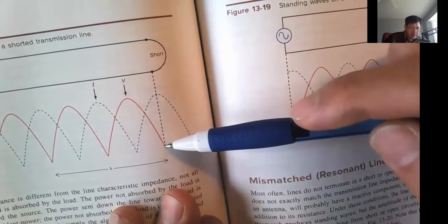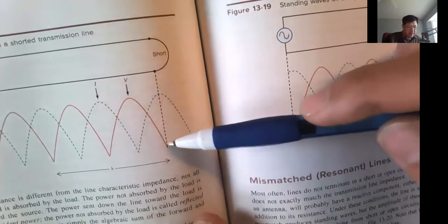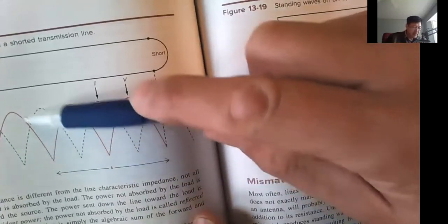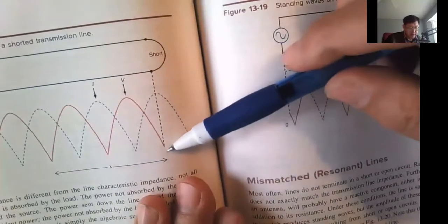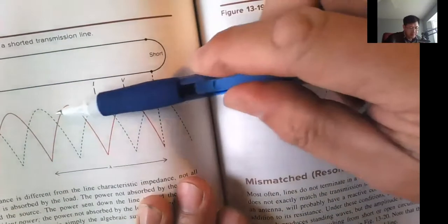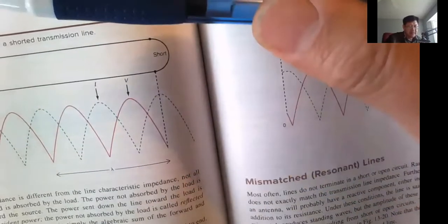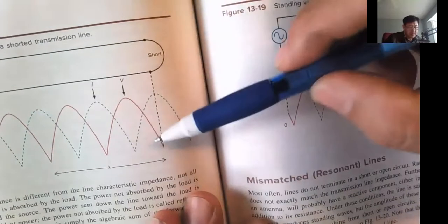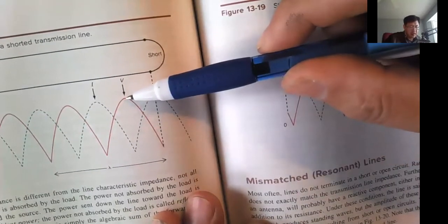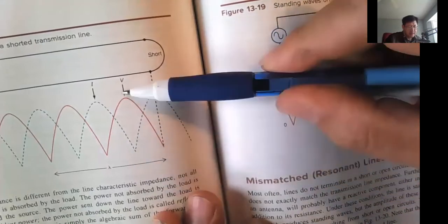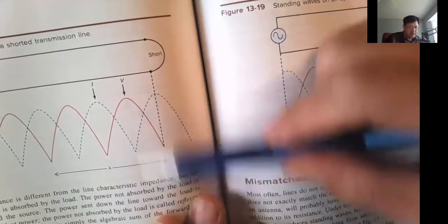And then what happens, the voltage is just like a wave. You have waves, so that's the wave. That's assuming the signal is at very high frequency. So that's the signal frequency. You have the half wave. This is called a standing wave. Why is it called a standing wave? Because the voltage here is always zero. The voltage here is always maximum. This is the amplitude of the sine. So here you have zero sine, here you have a little sine, and here you have the maximum sine.